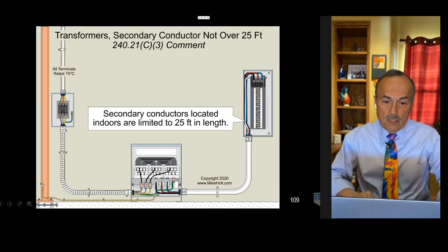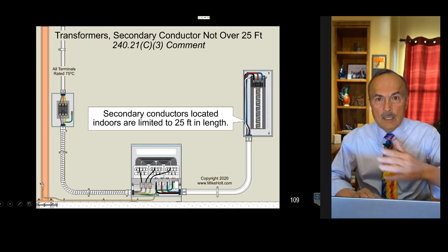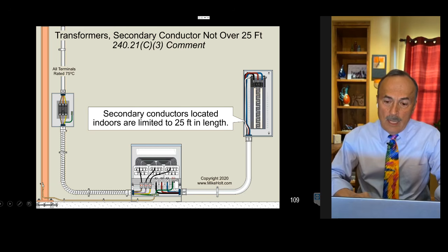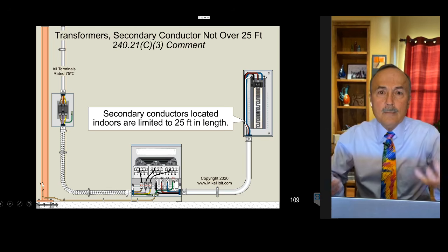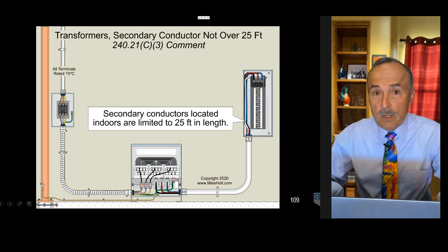What else we have here? We have plastic bushings. No, they don't have to be. We need insulating. We need to protect the conductors. Oftentimes it's going to be plastic. We'll be talking about that as the video goes along. Any pros of running a conduit? Listen, you run flex when flex is a good idea. You run EMT when it's a good idea. You run rigid when it's a good idea. You run PVC when it's a good idea.